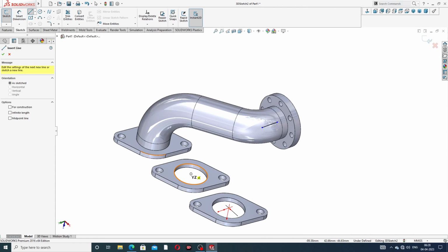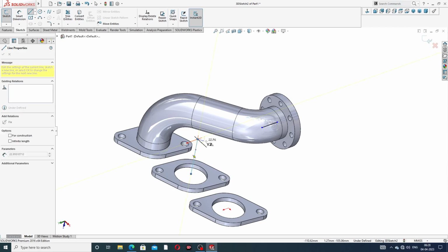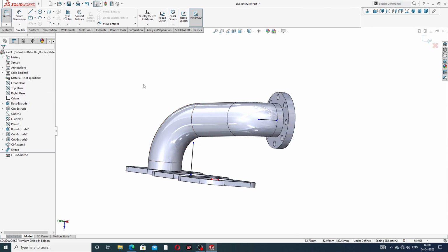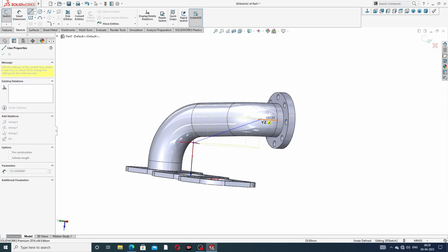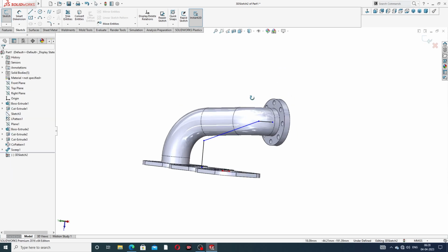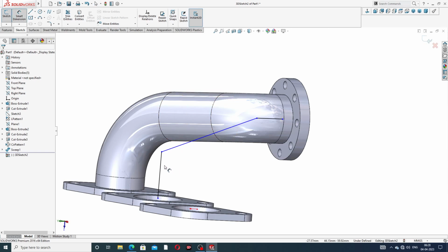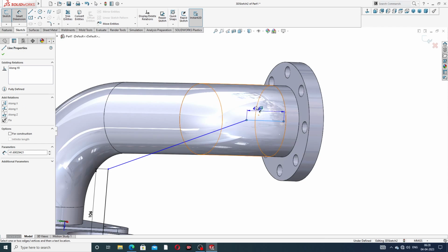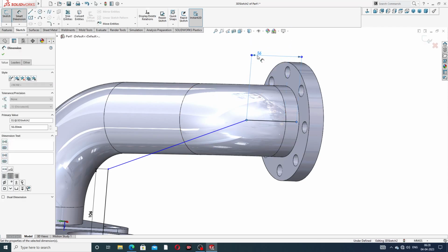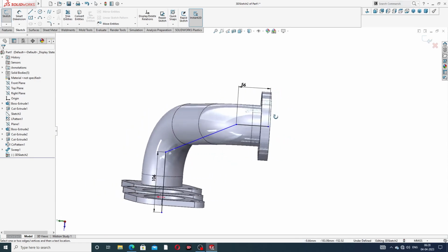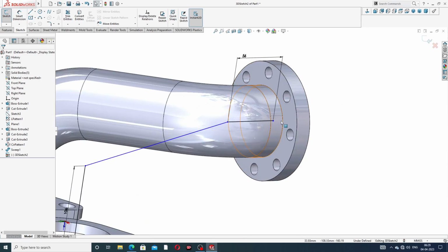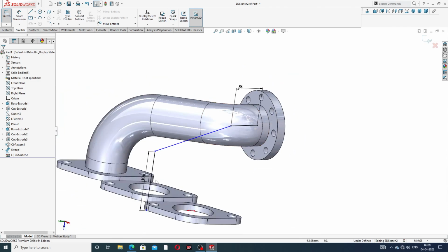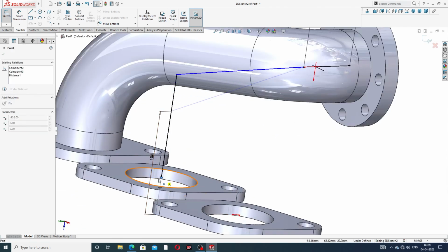this again select, and this use a center point, center line, and okay, this is a vertical line, okay, some drag here, and again select a line connecting this to this, okay, and this align dimension is the same here, 106 millimeter, and this uses 56 millimeter, which is correct, okay, but some points on both sides are dragged here, and connect to these two, okay, this use this, and again select this point to this, okay,